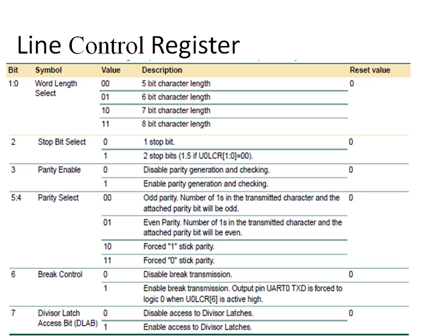Okay, so here you can use either 2 stop bits or 1 stop bit by programming this particular bit. In most of the cases we do use this 1 stop bit. If the peripheral is slower, then we'll be using 2 stop bits. Okay, and then the next bit is parity enable.